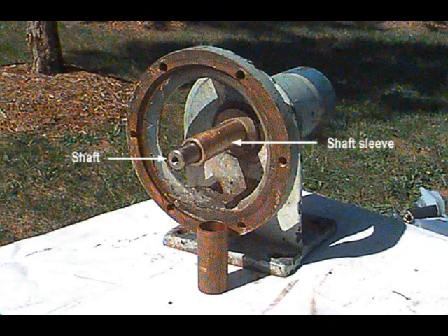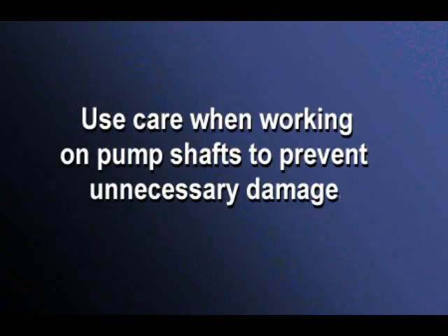Now we will discuss shaft sleeves. The pump shaft and one type of shaft sleeve are identified in this diagram. The shaft should be handled with great care. If working on or around the shaft, be careful not to damage the shaft. Also be careful to avoid unnecessary force or sharp blows to the shaft.